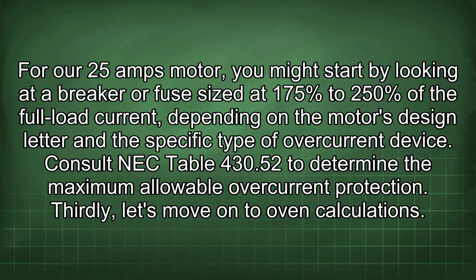For our 25 amp motor, you might start by looking at a breaker or fuse sized at 175% to 250% of the full load current, depending on the motor's design letter and the specific type of overcurrent device. Consult NEC Table 430.52 to determine the maximum allowable overcurrent protection.